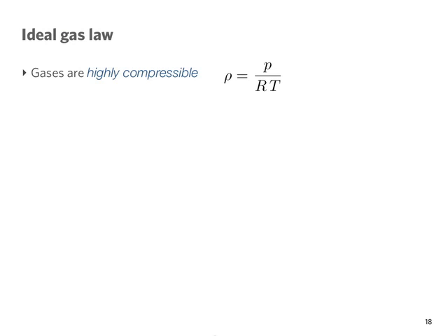Again, a reminder, and some of you are taking thermodynamics concurrently with fluid mechanics, so let's make sure that you remember your ideal gas law. So remember, gases are highly compressible. Liquids, on the contrary, are not. For gases, we have the ideal gas law. Rho is equal to P divided by RT, where P is the pressure and R is the gas constant, which you will find in tables of thermodynamic properties, usually in the back of your fluids book, thermo book. Those will be available.